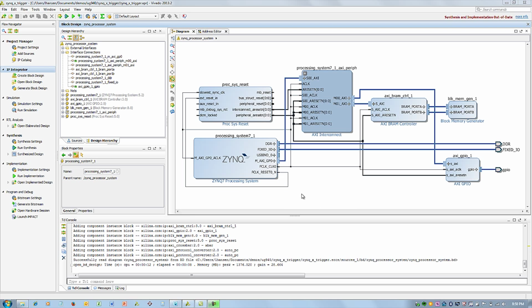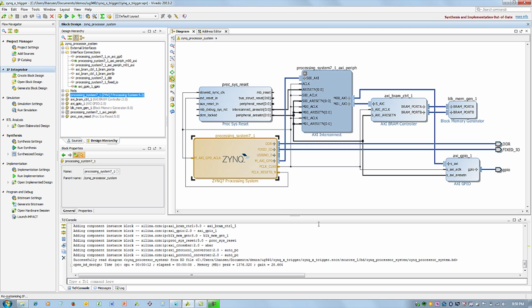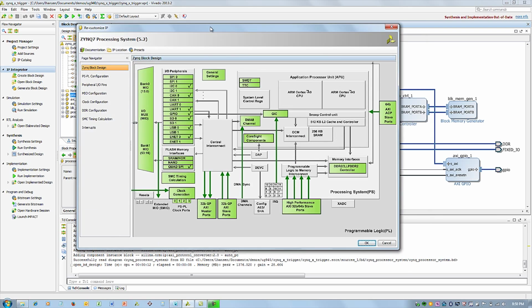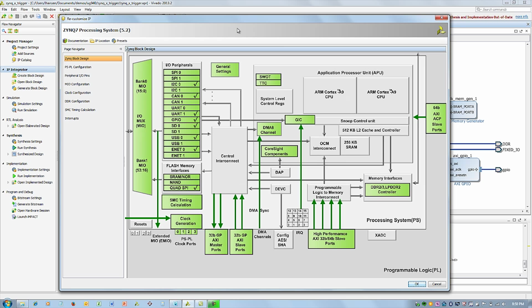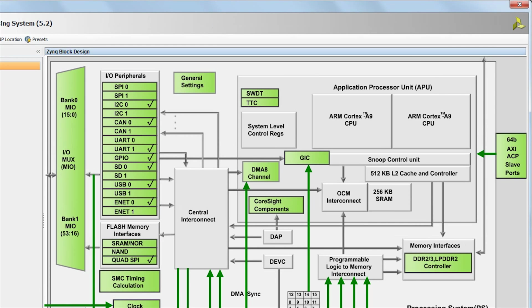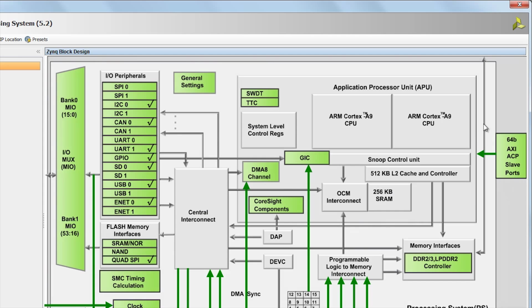The heart of our system is going to be a Zynq processor. This is the Zynq 7000 SoC all programmable device, dual ARM A9 cores, literally the most advanced ARM A9 systems out there for programmable logic. When I started this design, I told Vivado that eventually I would target a 702 board, a Zynq evaluation board, and it knew what peripherals were turned on that board, so it set those peripherals for me accordingly. I can configure interface, peripherals, like I said, clocks, literally anything here, and Vivado will write all that hardware information out at the end for me.